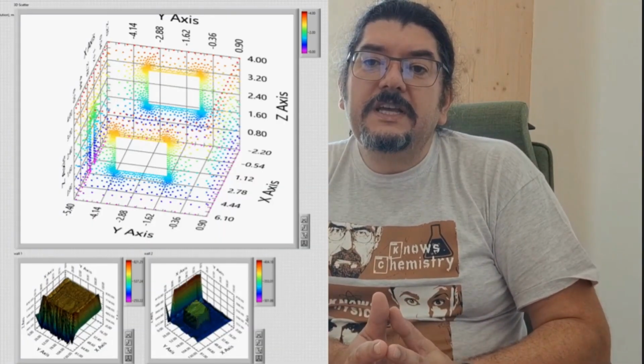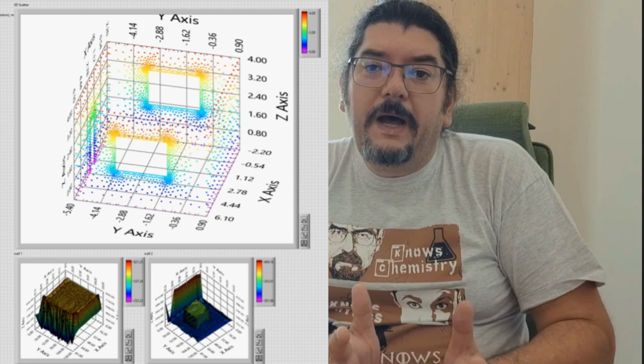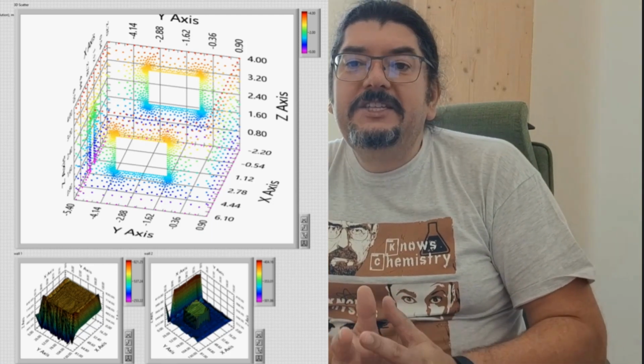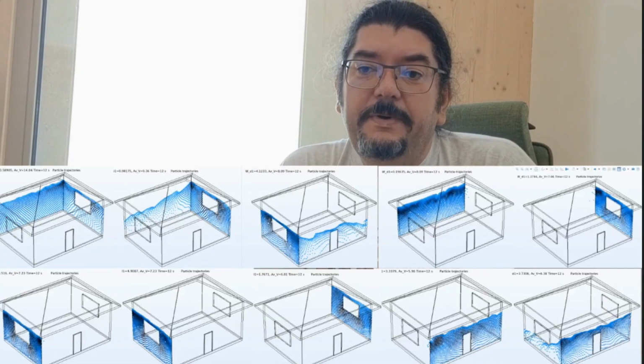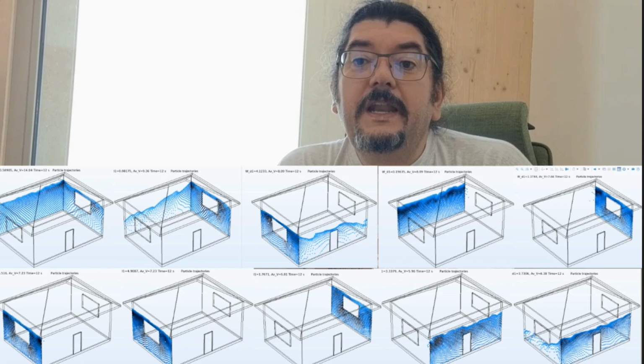Fortunately, building physics is very well established nowadays, and various engineering tools help us a lot to map material climate at each position over the facade surface. Finite element methods are perfect for simulation of temperature, solar radiation, as well as wind-driven rain. Therefore, we managed to properly identify dose distribution over the entire building scheme.